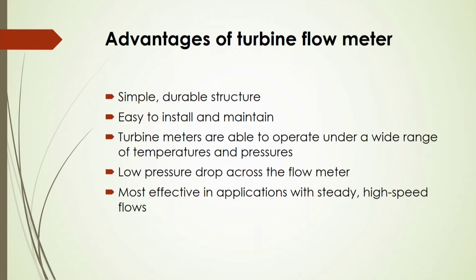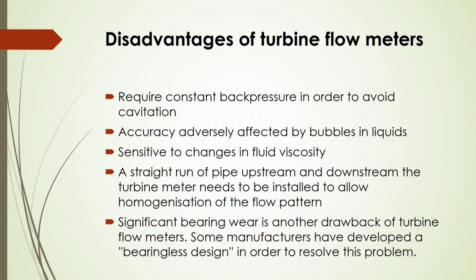And what are the advantages of this turbine flow meter? Generally, you will see it will be very simple, durable structure, easy to install and maintain, and also turbine meters are able to operate under a wide range of temperatures and pressures, low pressure drop across the flow meter, and most effective in applications with steady and high speed flows.